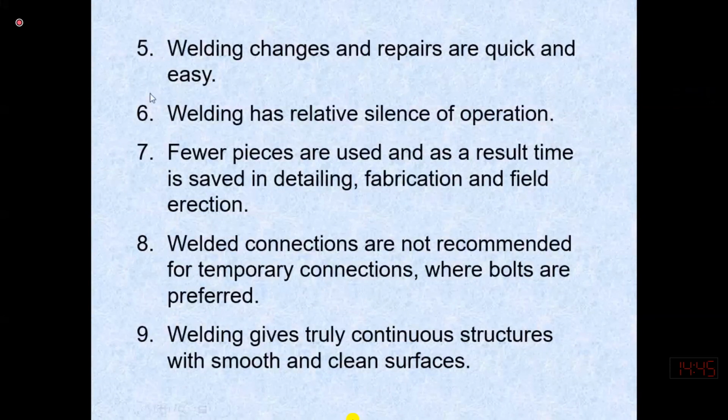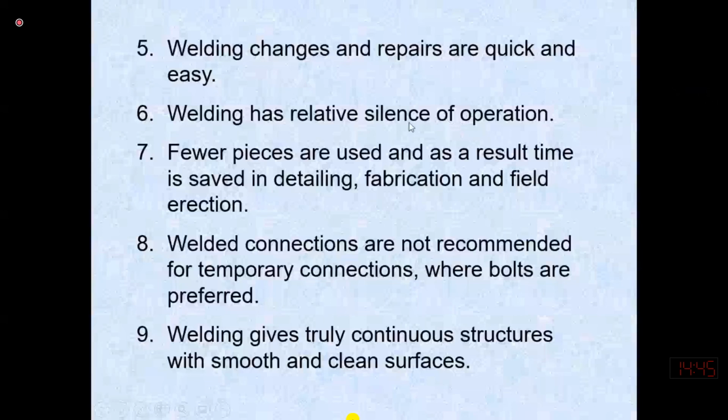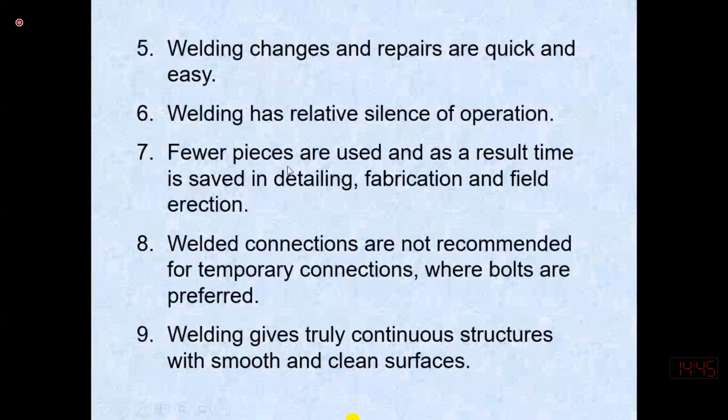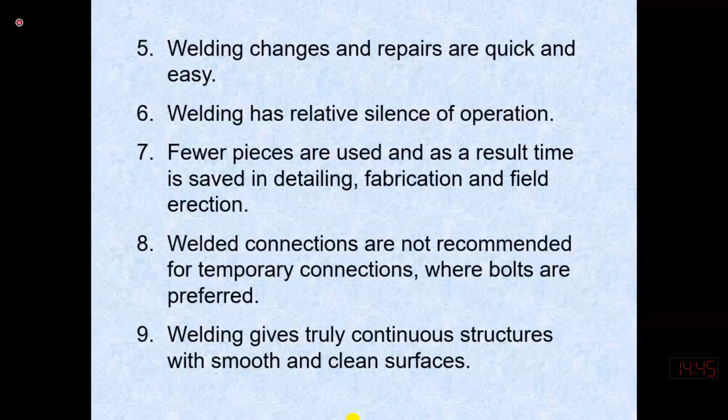And welding is a relatively silent operation, but riveting, as you have seen in the video, is a much noisier procedure. Fewer pieces are used, and as a result, time is saved in detailing and fabricating in the field. So welding is a quick procedure. Other types of connection may take more time. You may argue that bolted connections can easily be accommodated, but you need to punch the hole. Punching the hole to install the rivet itself takes a lot of time.